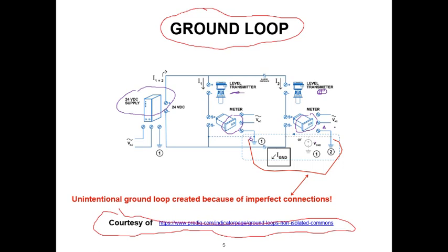Anyway, if you go to the site, and I recommend that you do, and I just found them online, they say that they're assuming that there's a poor ground connection here. Maybe the terminal screw is loose or some other problem, right? And there's a difference of potential between that point there and that point there. And obviously, this should all be zero between them, but it's not. And you can have many volts of potential difference between two ground points, depending on how severe the case is.